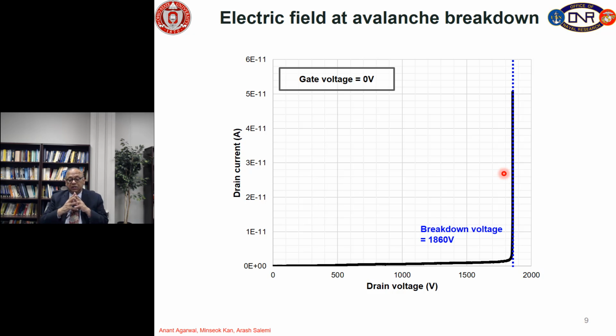So, this area is called the avalanche voltage and avalanche region, and if you recall that in the avalanche region the electrons and holes are accelerating in opposite directions under the applied electric field in the drift layer, and when they acquire enough energy they knock off an electron from the outermost orbit and create another electron hole pair which accelerate again and create more electron hole pairs under this high field, and therefore this is a positive feedback process, just pretty much like the nuclear fission reactor, and the current increases rapidly.